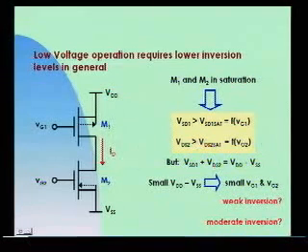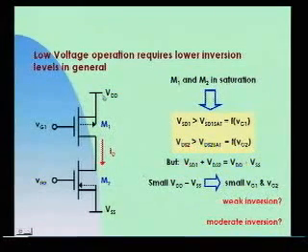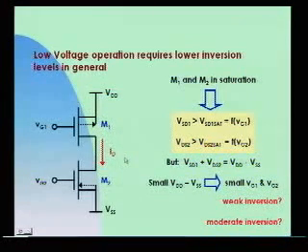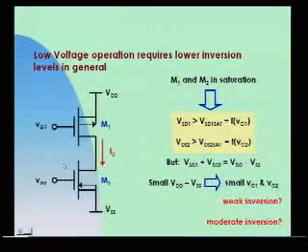And for example, in this circuit, if the voltage drop between these two terminals is low, that is VDD minus VSS is low, and I have to, for example, put these two transistors in saturation, I will need to have the VDS drop between the terminals high enough, and to do this, the VG voltages must be small.